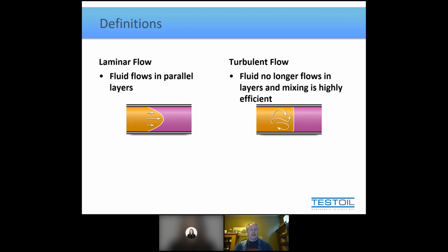And when you think of fluid as being laminar flow, that's kind of the same premise. You can see in the graphic the fluid down the center of the pipe, and in this case, the layers aren't stacked because they're going to be circular, but the flow will go through the very center of the pipe quite nicely. But as you get closer and closer to the walls of the piping, the fluid's going to move less and less because it'll have less friction against itself. And there's going to be almost no movement, relatively speaking, towards the walls of the piping. So my point is, how do you expect that to pick up particulate and anything else within the system?